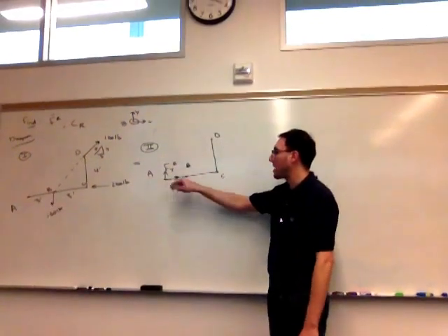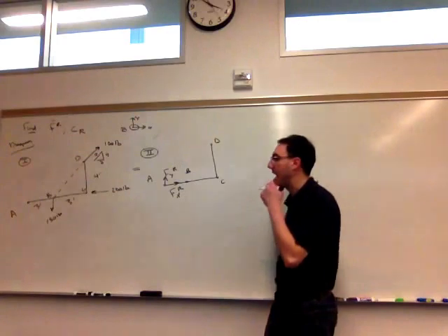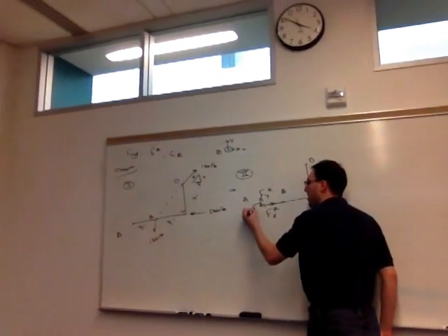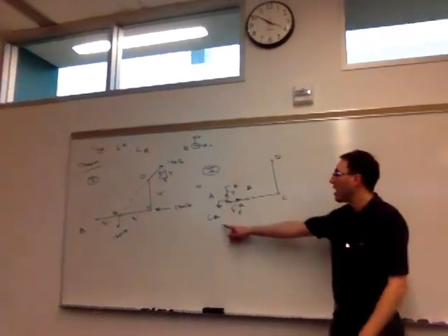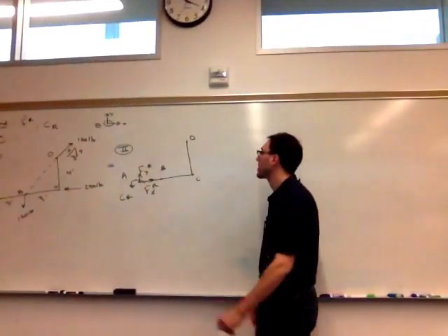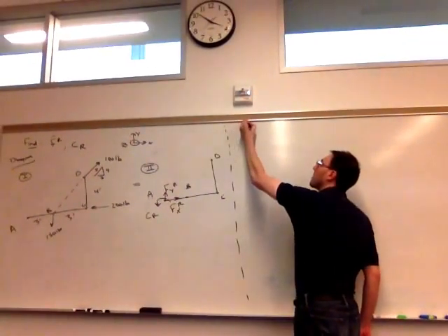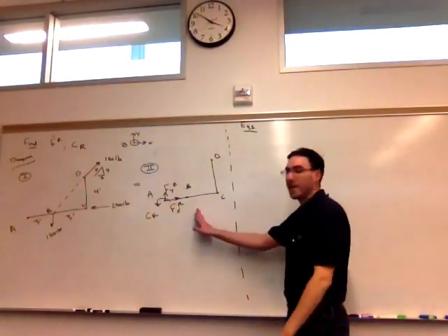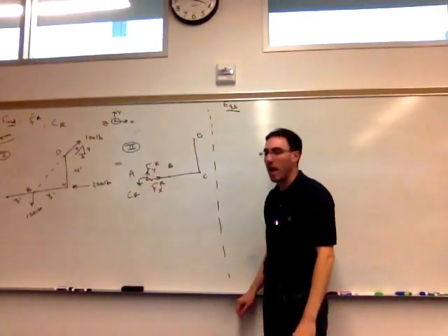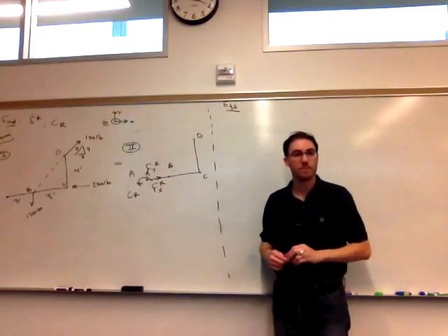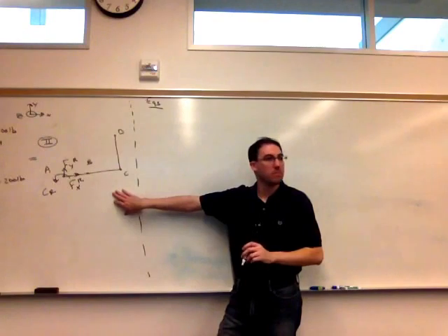So there's my force acting at A, already in component form, and a couple acting at A. I'm going to assume, for the time being, that it's positive, so counterclockwise around point A, I'll call it CR. And that's it. That's my simplified system. One force in component form right now, and one couple located at A. Questions about my equivalent system for this problem?